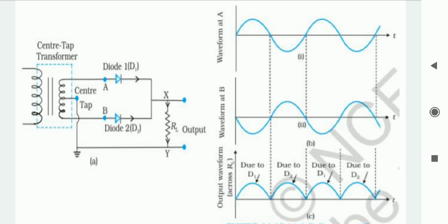For diode D2, the P type is connected with the negative terminal at point B and the N type is connected at the neutral point 0, and 0 is positive in comparison with the negative voltage. That's why diode D2 comes into reverse bias condition. So while the positive half cycle is given to the input, only diode D1 will conduct, and we are able to get the output voltage as we can see in the graph in diagram C.